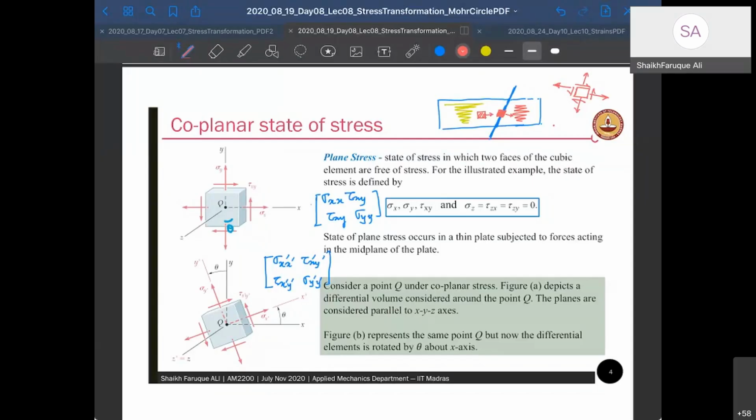For example, we took a bar member. When I say a bar member, it's an axial member, and there was a P force here. We chose a small area here, and the stresses were along this direction, here, and the sigma here. And we saw that the sigma along your axis changes like this if you have this angle of orientation theta.